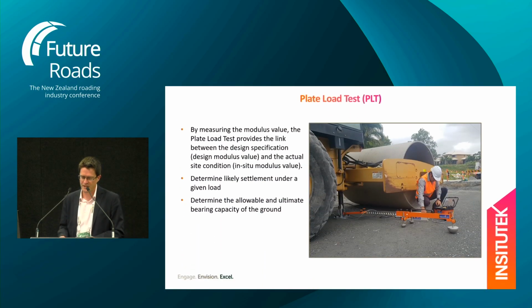So plate load testing. This is a base test, if you like. This is probably the most sophisticated setup that you will find in the marketplace. Essentially, we've got a counterweight, like a roller or an excavator or something like that.